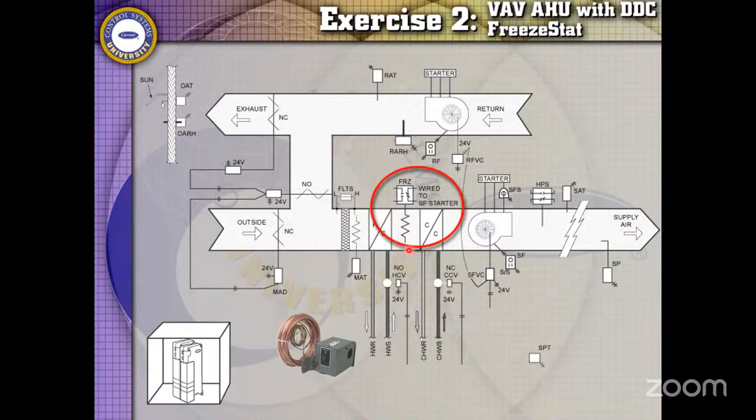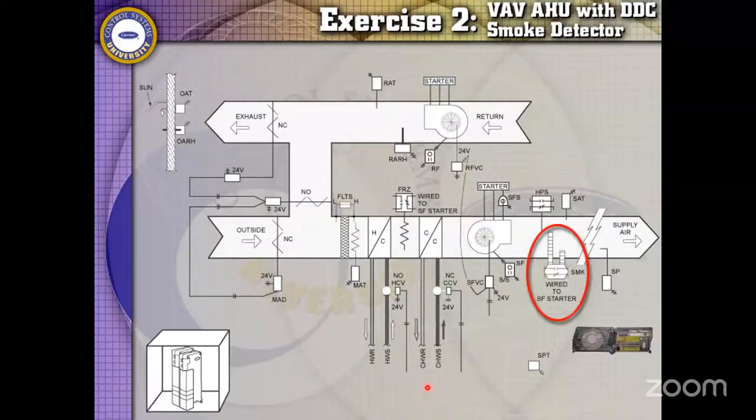That's not good. So we want to open up this valve, which means cold 44-degree water from the chiller is going to flow through here, but 44-degree water doesn't freeze, right? So I want the 44-degree water to start flowing through this thing because that's not going to freeze. The chilled water is literally warmer than the cold air at this point, so I'm going to take it, right? Plus, moving water is kind of tough to freeze anyway. I'm constantly getting new water and sending it back into the building to accidentally warm it up.